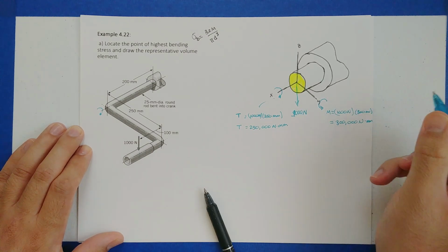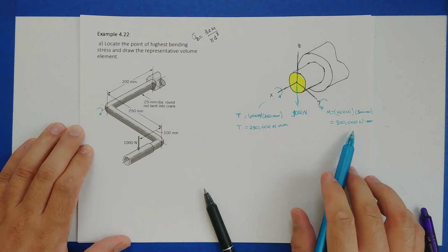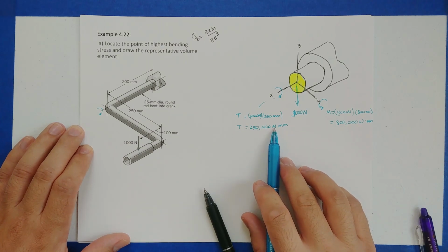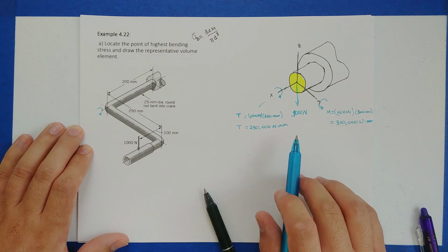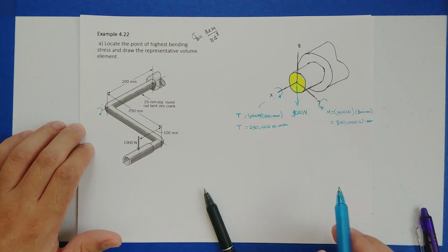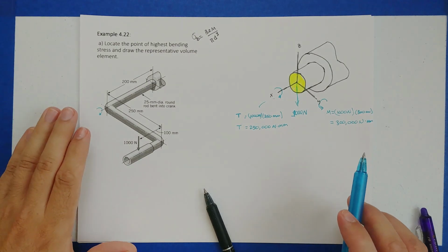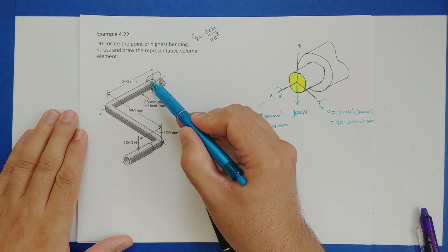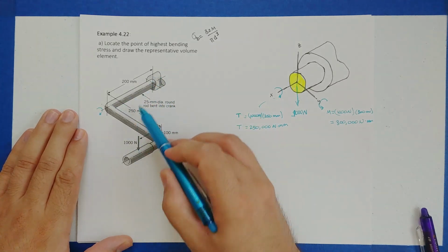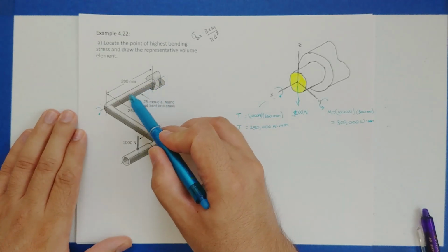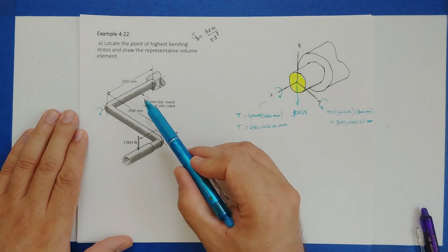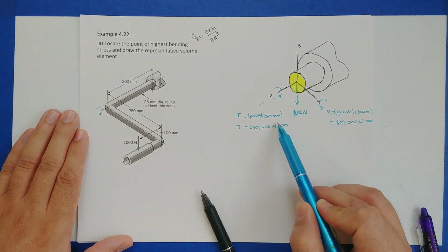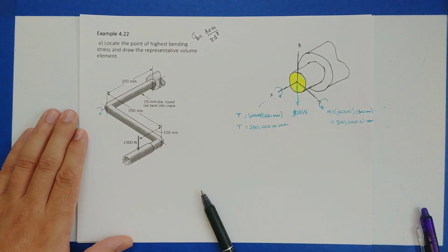Newton millimeters. Now, usually you get some warning signs in your head, like boop, boop, boop, this is a way too big number, and the unit Newton millimeter for moments is kind of weird, but you'll see it's going to work out for us in this case. At this moment, if you want, pause the video and section over here, look at the front part, and figure out those reaction forces to make sure that this front part is in equilibrium. Then you should be able to check that the forces and moments you get are exactly the same magnitude as this one's, but in the opposite direction.